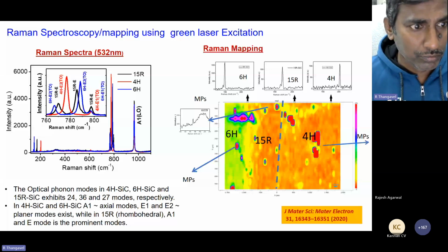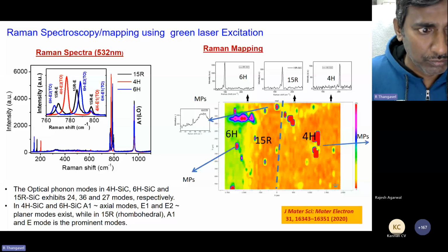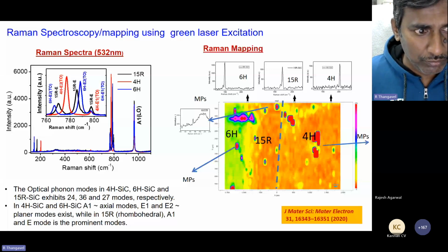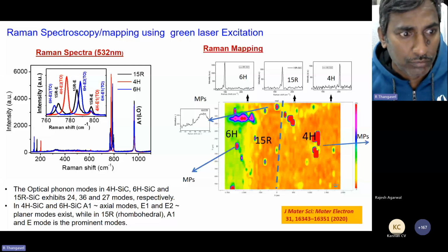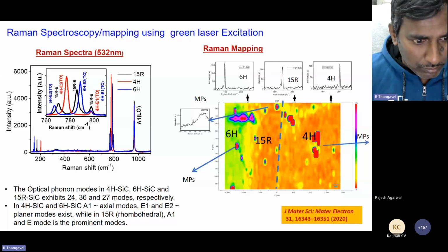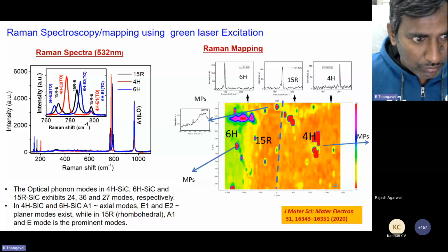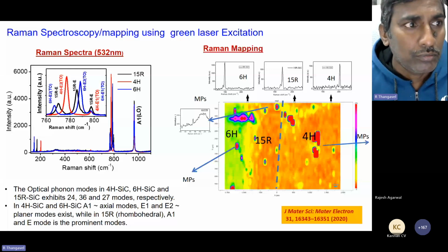It has to be a clean room, and depending on the device, the clean room class has to be changed for the processing room. And surface preparation is also very important because mechanical and chemomechanical polishing has to be done. Using chemical and chemomechanical polishing, surface preparation is very important to fabricate the device.